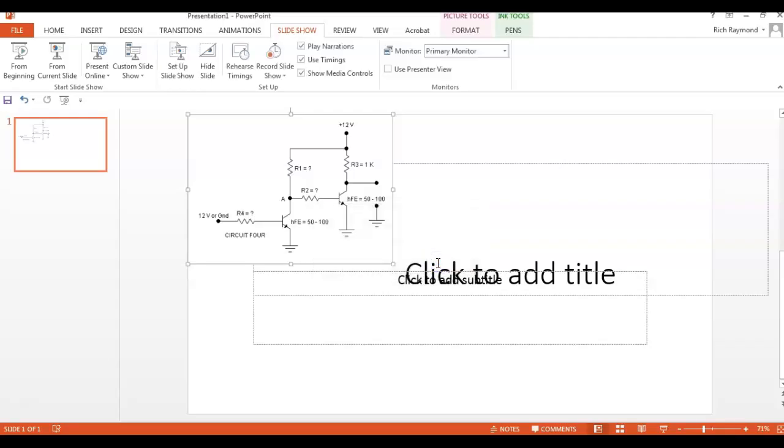But y'all know how to identify saturation, right? What measurement do we use to identify saturation? That voltage, collector emitter. If it's less than a volt, we assume it's saturated. If it's equal to what we call VCC, whatever you put up on the collector, we say it's cut off. If it's between 1 and VCC, we say it's in the active region, which is where your amplifiers work.